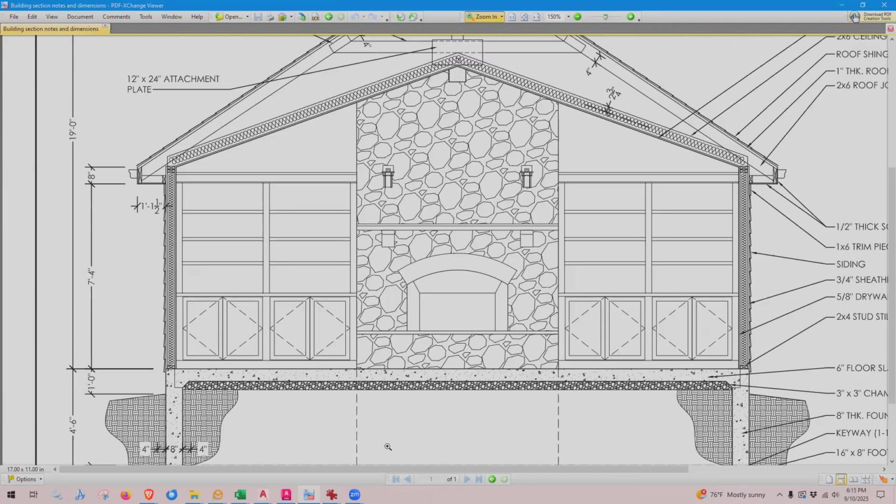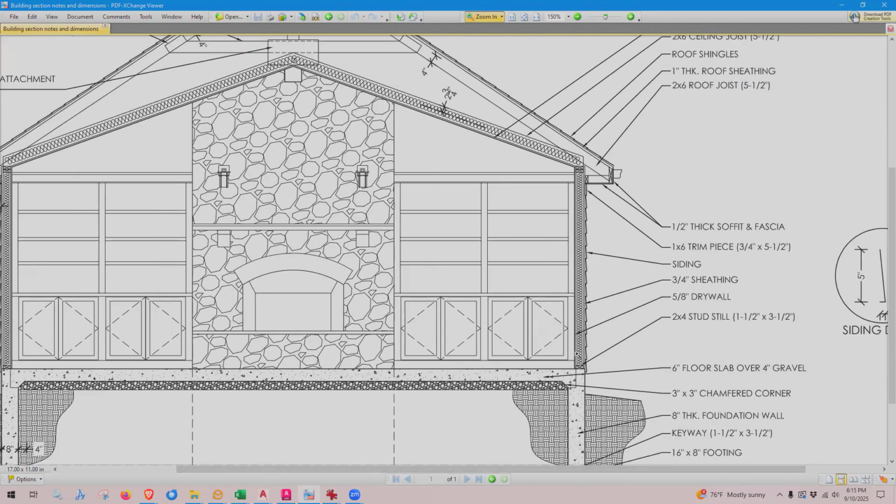So, all right, then we build the walls, and the walls are comprised primarily of 2x4s. You may have heard of the term 2x4. I'm sure you all have heard of it. And those are studs, 2x4 wood studs. They run along the bottom and the top, and then between them, every 16 inches is another stud, and that runs along the full length of the wall all the way around the building.